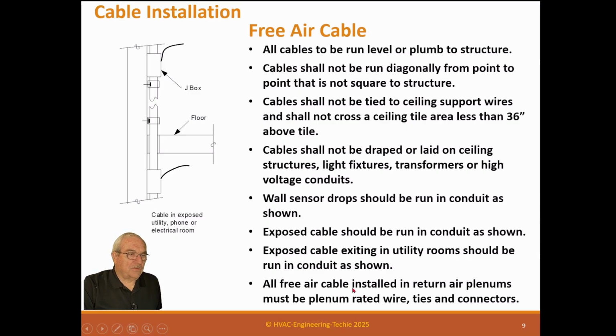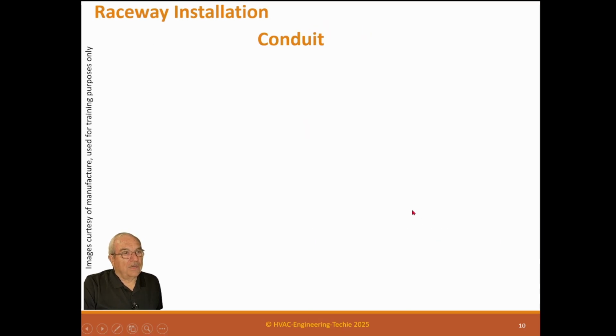In our trucks, when I was a control contractor, we only used plenum-rated ties, not wire, because that's more expensive, but the ties and connectors were all plenum-rated. We didn't even let the guys have any standard ones. That made that safe. So conduit.